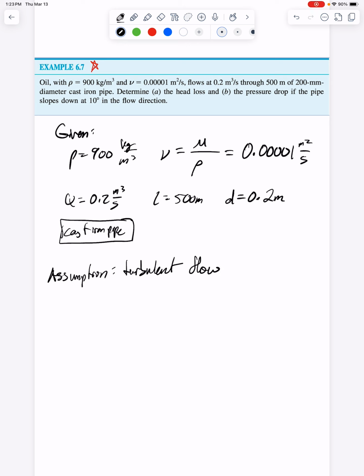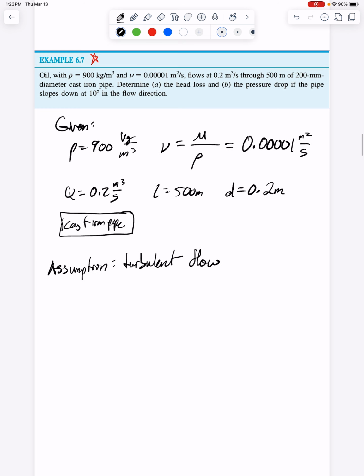Yes? Would changing pressure also entail turbulent flow, or does that not? You're saying pressure difference? Yeah. Because pressure difference is needed to drive a flow. So even laminar flow needs pressure difference to have velocity. Otherwise, there'd be no velocity. So yeah, at least for me, it's the detail of the pipe.